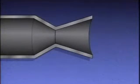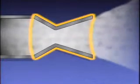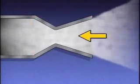This is easier to understand if we look at how a rocket engine is designed. This simplified illustration represents a nozzle that is part of a rocket engine. Hot gases from the combustion of fuel are exhausted through the nozzle as they leave the combustion chamber of the rocket. The nozzle causes the hot gases to accelerate to a high speed as they pass through the nozzle's narrow throat and then expand. The high speed creates a reaction force on the rocket engine that is in the direction opposite to the movement of the gases. This reaction force propels the rocket engine.